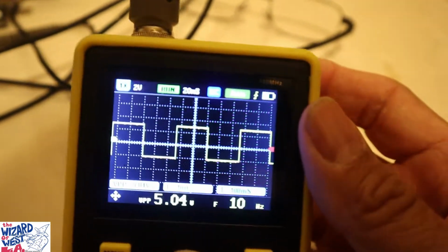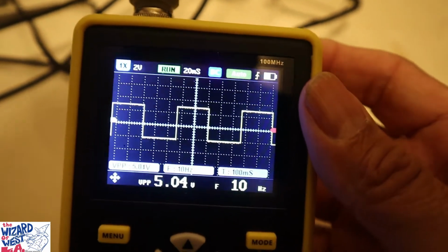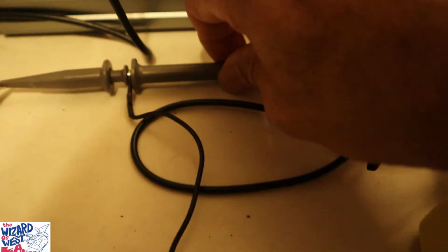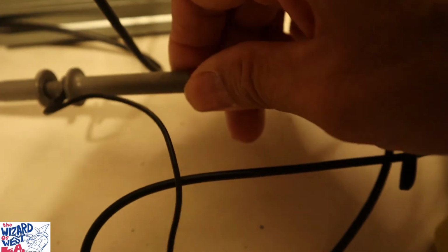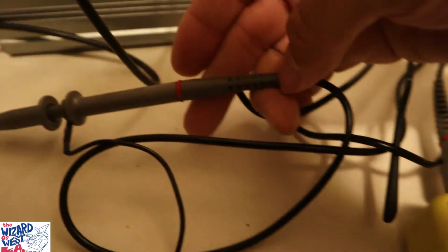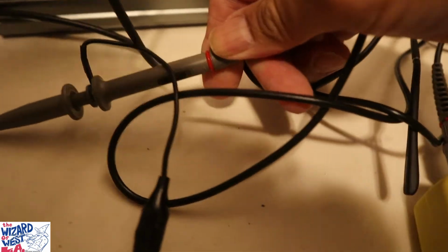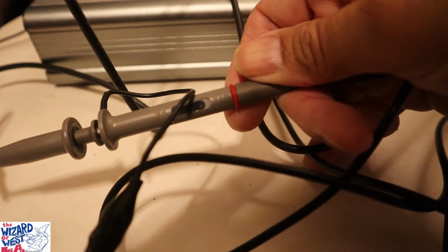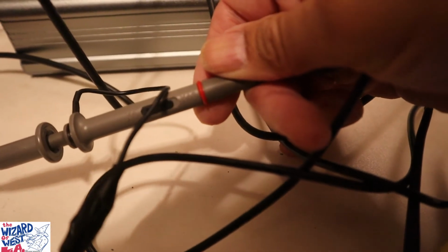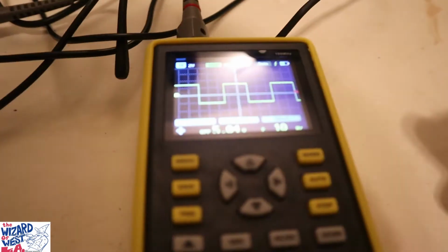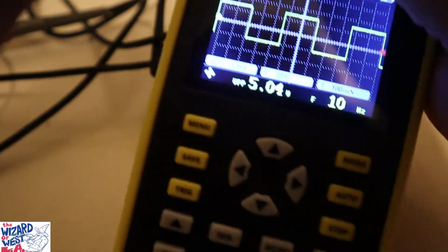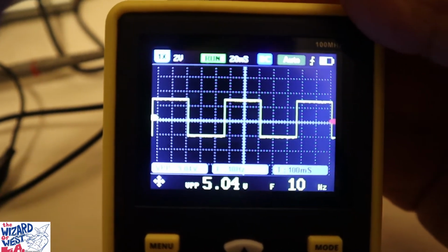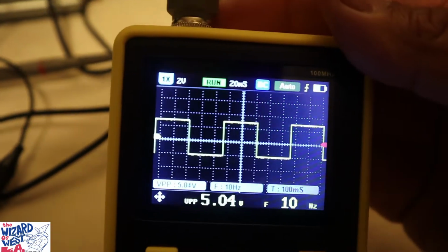So hope you had fun with the video, taking a look at what an oscilloscope does. And one extra thing I want to add is on these probes, you have a switch right there. It says times 1, and then you have like times 10. Those are to run it at higher voltages, and right now we're running only 5 volts. You can run some of these up to 80 volts or more, but you have to change that switch, or else you burn out the meter.